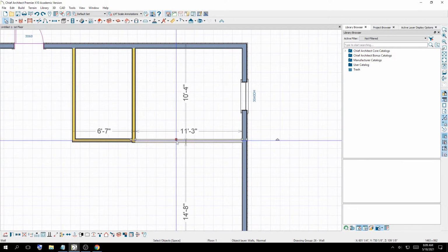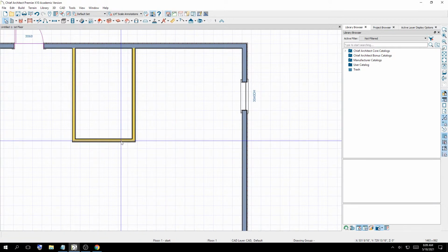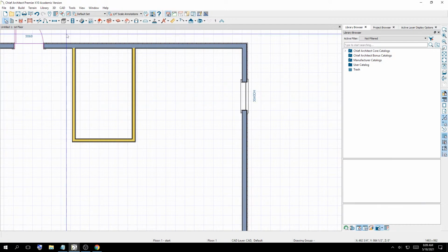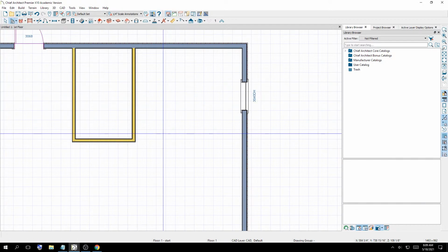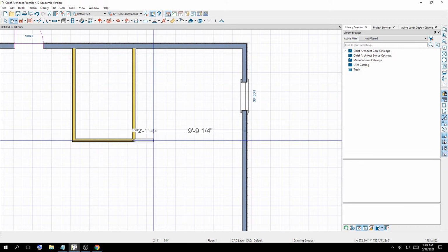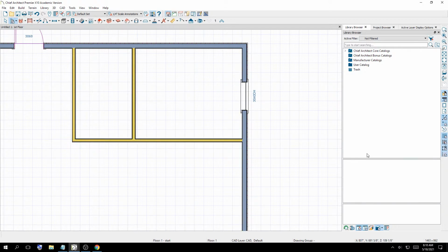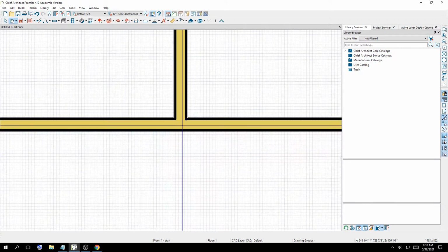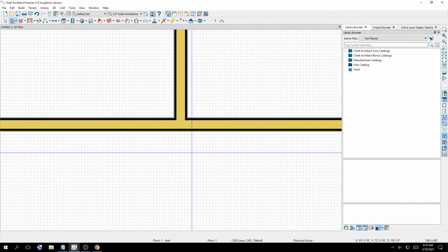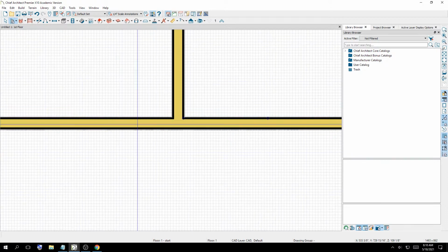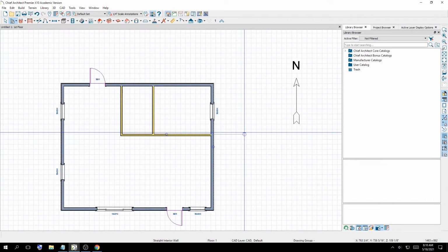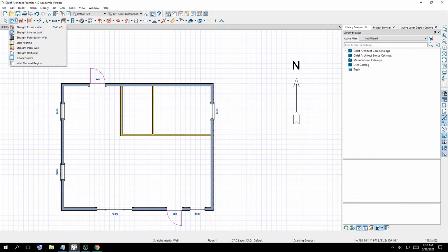What I would do, actually, just because my measurements aren't that important, I would just delete the wall that was off, grab my specific corner, and I'm snapping at this point. You can see now it looks perfect. I don't have the inaccuracy. So if you have a misbehaving wall, just delete it and then redraw it with a snap, and you won't have this problem. Okay. Let's see.